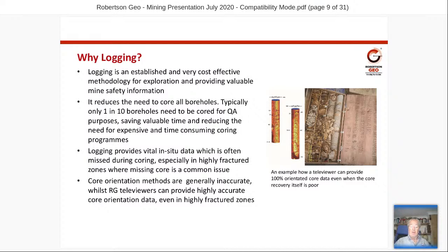The other advantage of logging, particularly with the new generation of televiewers, is for core orientation. And televiewers are able to provide orientated data even in highly fractured zones. So where you have a combination of core and image data or logging data, this provides an excellent picture of what's going on, and the logging data will fill in where you have zones of poor recovery.